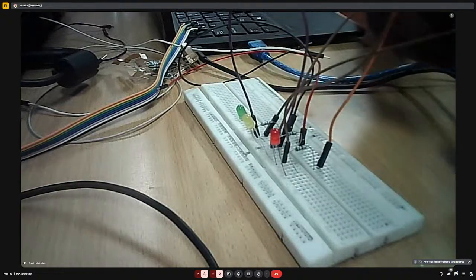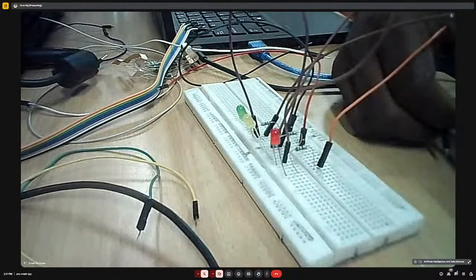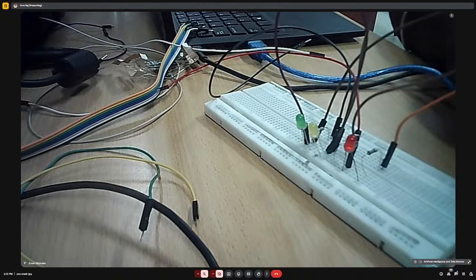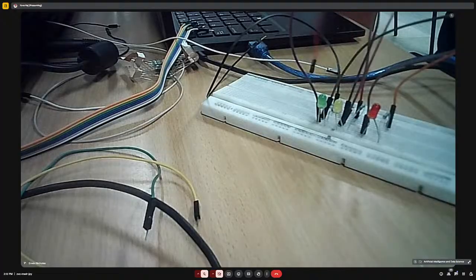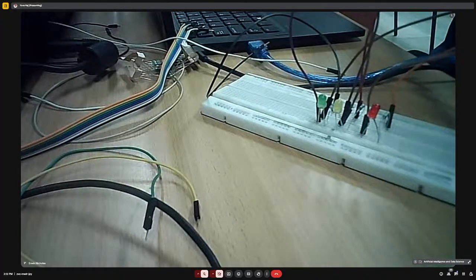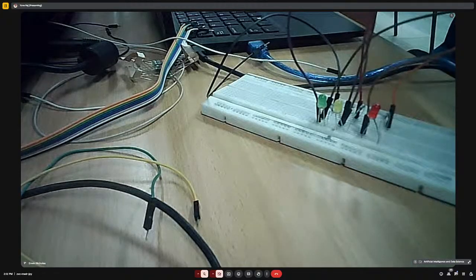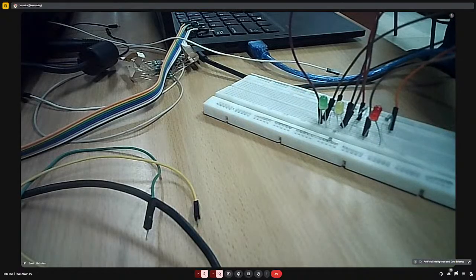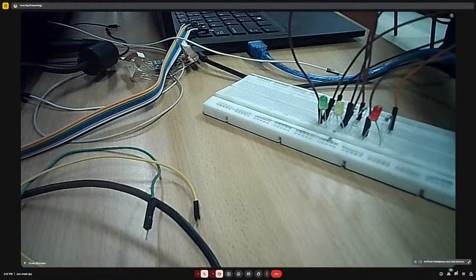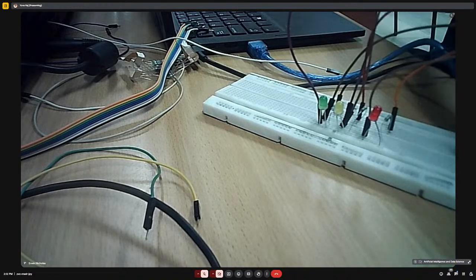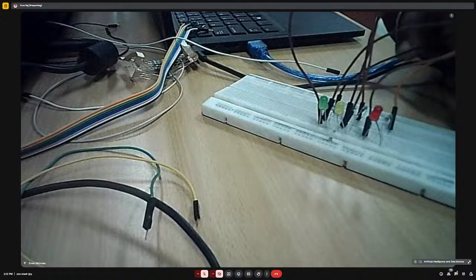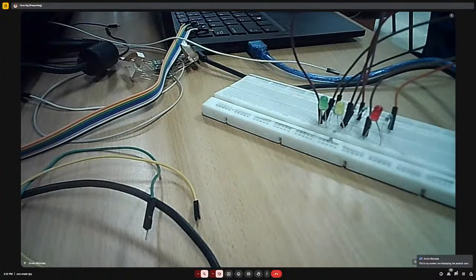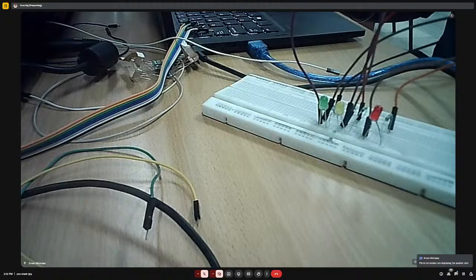The first LED pin, you can choose to connect to any of the digital pins. So I will choose the first one as 10, and then the second pin connected to 9, and the third pin will be connected to 8. So totally we have chosen three digital pins and one ground connection. Now go to the program.